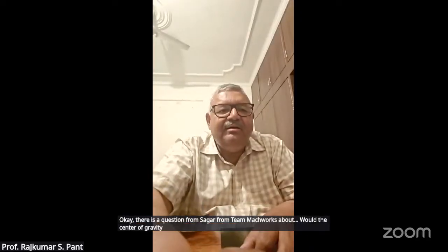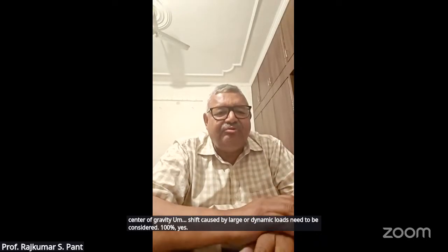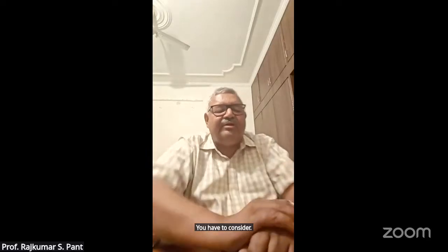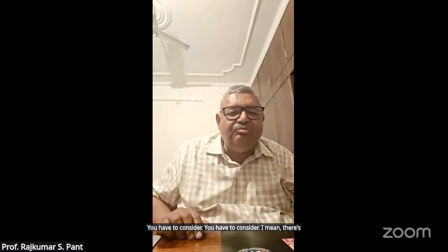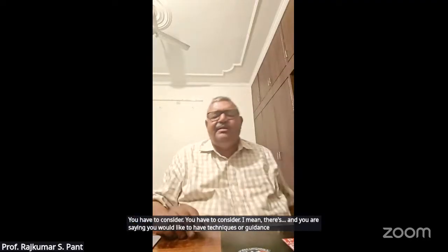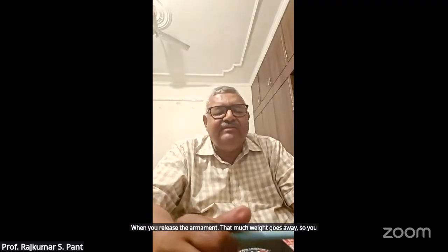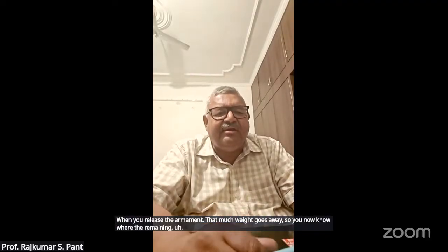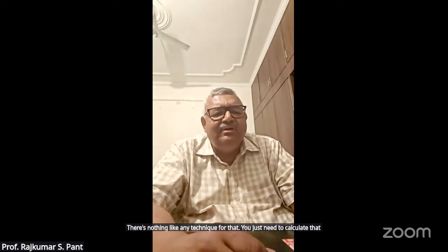Okay, there is a question from Sagar from Team Markworks about whether the center of gravity shift caused by large or dynamic loads needs to be considered. 100% yes, you have to consider it. You are asking for techniques or guidance. Very simple: when you release the armament, that much weight goes away, so you now know where the CG of the remaining aircraft is. There's no special technique for that. You just need to calculate it. So CG will shift when the armament is released.